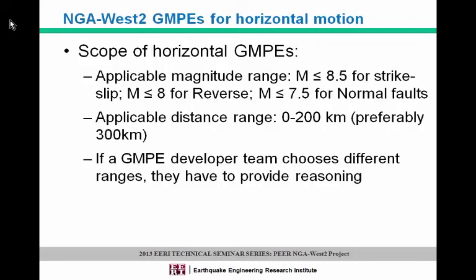One good example is using aftershocks. There are a couple of GMPE developers that didn't include aftershocks in their analysis. Now, statistically, we understand that if you have a main shock, hypothetically magnitude 6, and you have an aftershock, hypothetically magnitude 6, even though the magnitudes are the same, ground motions overall can be different. And a couple of GMPE developers said the important thing for the community and for us is the main shock.